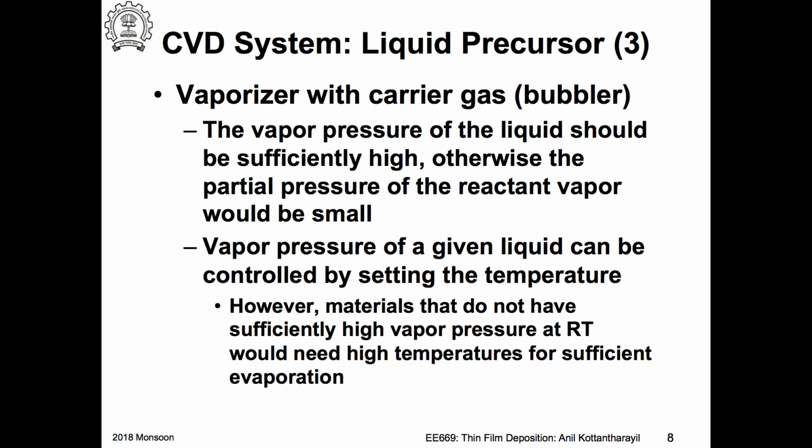Its goal is just to transport this into the reactor. So you can ask, for example, why should I use a carrier gas in the first place? I just heat the whole thing, right? I get a vapor. So then it would be maybe difficult for me, since it's 100% the vapor of this. But when I'm using a carrier gas, it can carry, meaning increase the vapor pressure, so even at low temperature, I can get sufficiently high vapor pressure. So that's one thing.